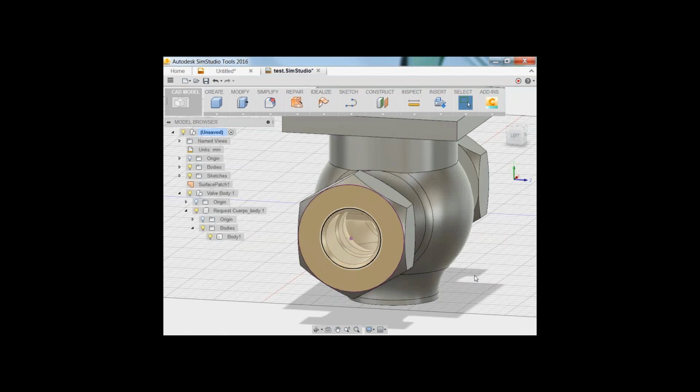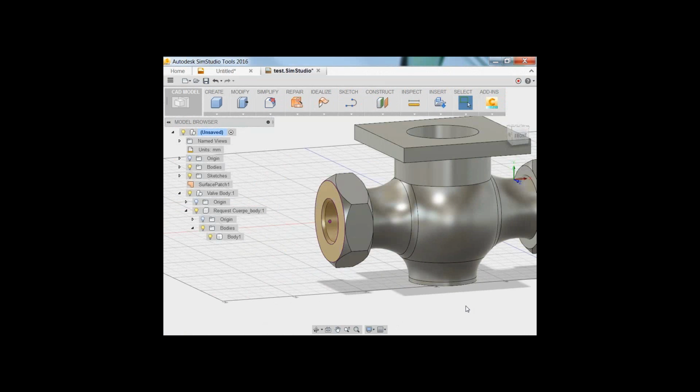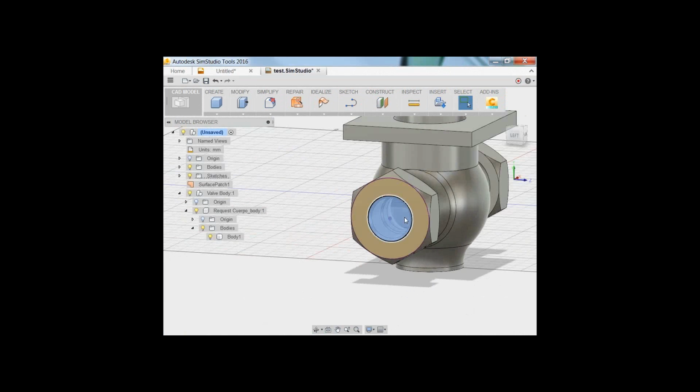And a sketch is not a surface, so don't get that confused. You can't actually do anything with sketches. It just exists. You actually have to make it 3D if you want to do anything and make it a solid. So here's a quick little example that I like to prove, which is the press pull.